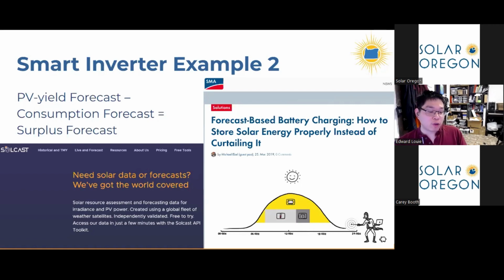And so if we don't sell a lot of power back to the grid, then there will be no space in the battery, like it's already full. If it's a very sunny next day, then you want to actually sell some of even the energy in the battery to the grid, so that it's low enough that the next day you have space to put the excess kilowatt hours from the sun. So there are now inverters available, like this, SMA makes inverters that can do forecasting and take the forecast into account.